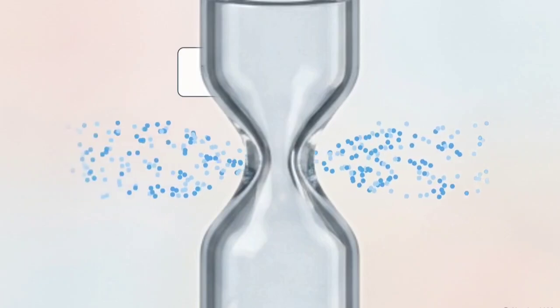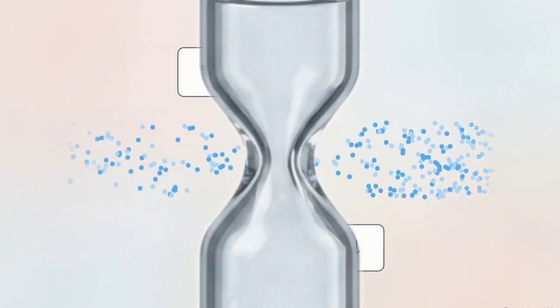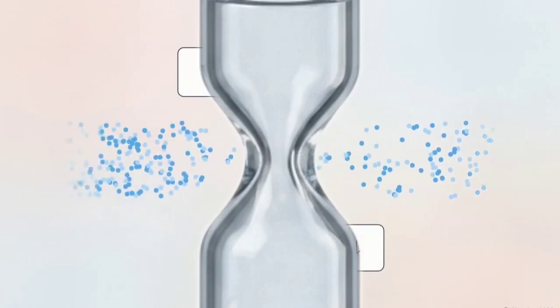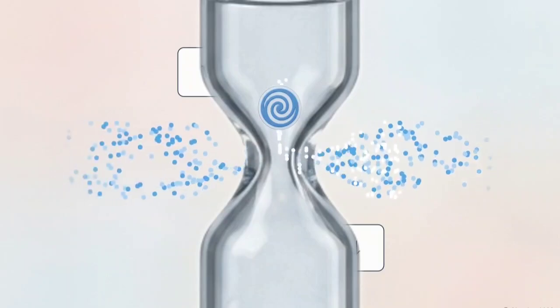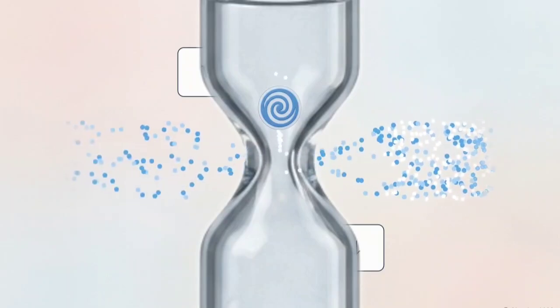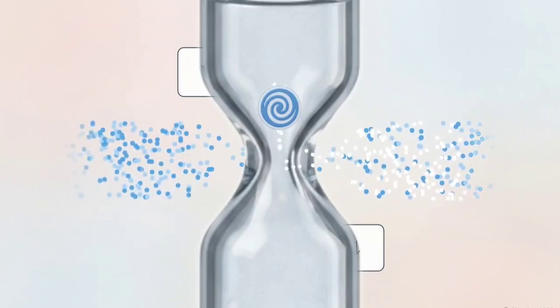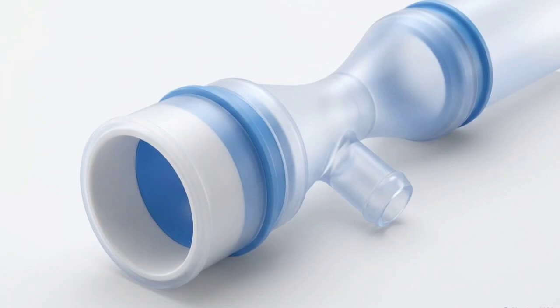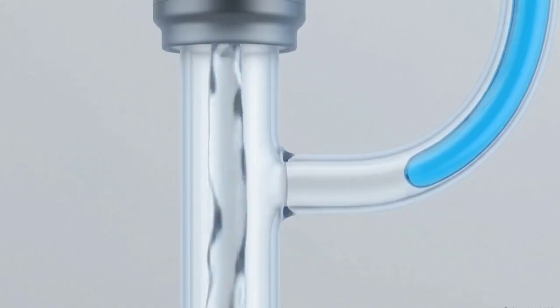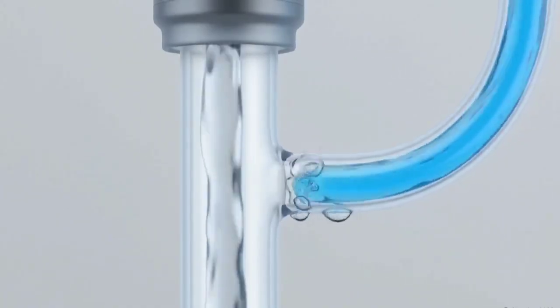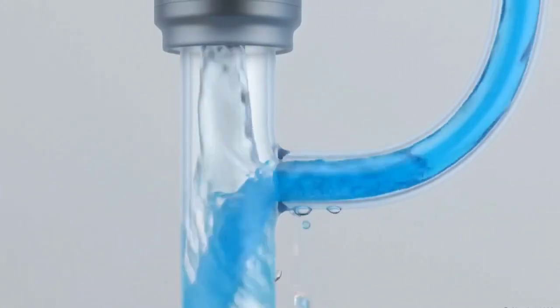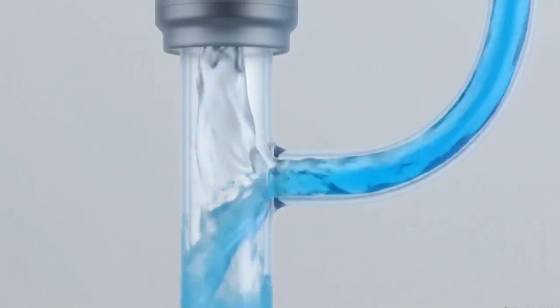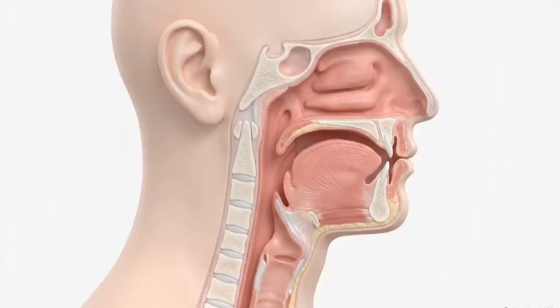If we create an opening at this exact low-pressure pinch point, the drop in pressure becomes so significant that it sucks outside air directly into the main stream. Any apparatus that combines a tube, a constriction, and an opening like this is known as a Venturi apparatus. In this specific configuration, the high speed of the gas creates a powerful suction, effectively transforming the pipe into a pump. This explains why the airway collapsed in our earlier example.